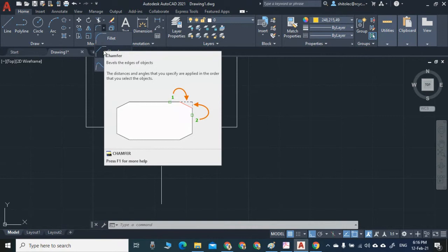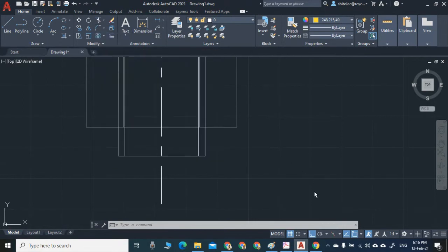So triangle, how you can draw triangle? If you have the two lines, then you can join the third by two end points. So like this chamfer. So I have here angle and length. Teacher, where is length? This is the length from this point to this point. So I will click on chamfer, and read here. Select first line. No, undo polyline, distance, angle. What you have? Angle. So I will type angle A, enter.